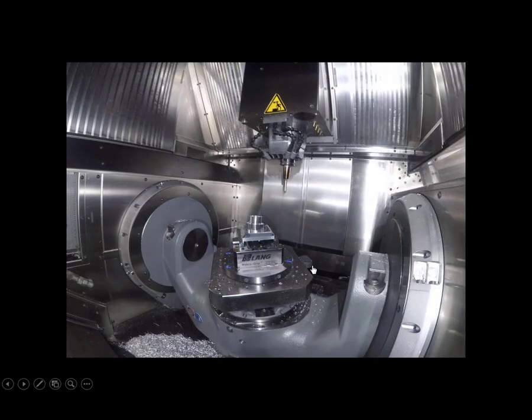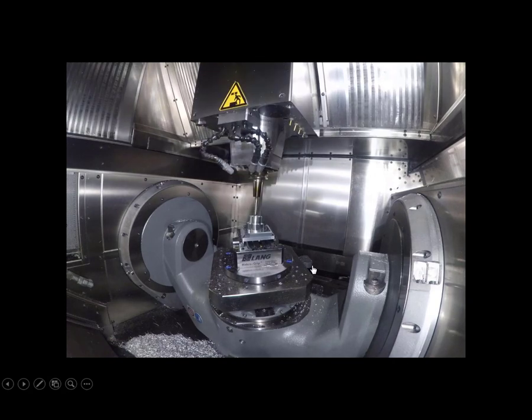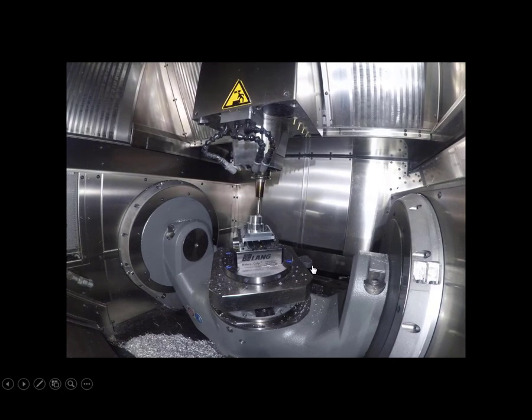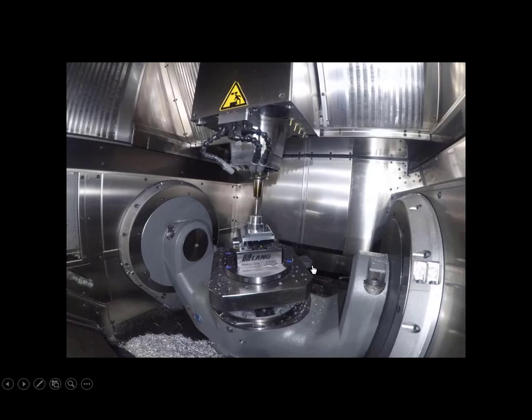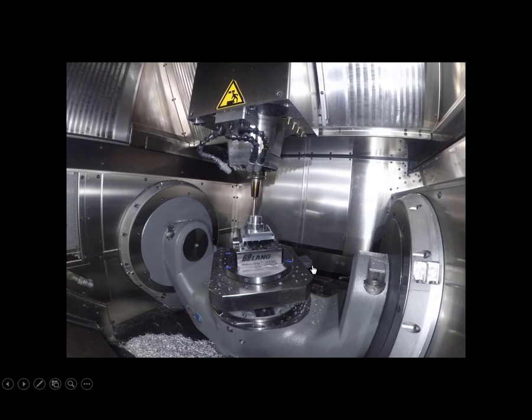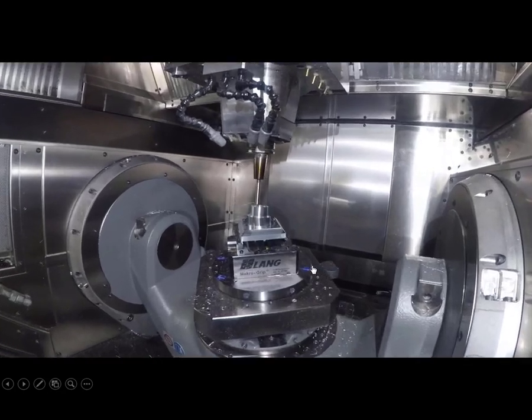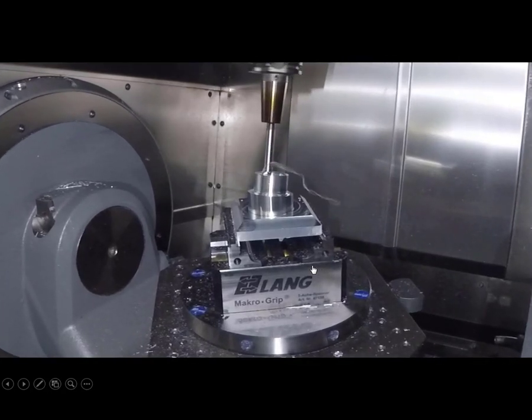And in the next step, we do the same with a turning tool. So interpolation with a turning tool. So orientation, and then the machine will do a movement, and now it depends on how fast the machine can handle this. The cutting speed depends on this.